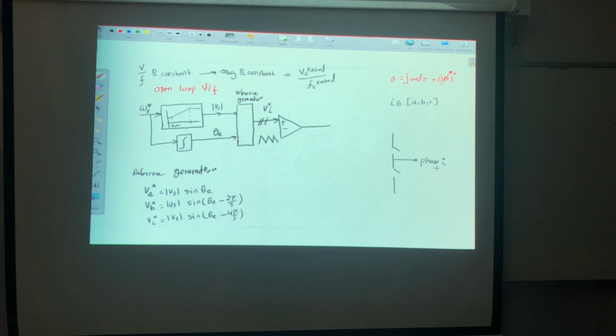So assembly here, if this is phase I, this will be the higher switch of phase I, and this will be the lower switch of phase I, correct? And you know that in general I'm having 3 legs connected in parallel. So let's assume that this is the positive terminal and this is the negative terminal of the DC side.